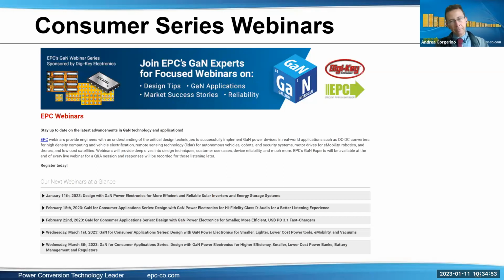Okay. Next question is, what kind of process are you using on your GaN ICs? Is it CMOS or BiCMOS for logic and GaN for power MOSFET? Single die, or is it hybrid? They are actually all GaN. There's a little picture here. This is one of our first ones that we did. These are the FETs, and this area right here is basically the GaN IC. So it's monolithic. It's all made in GaN. So it's GaN IC technology.